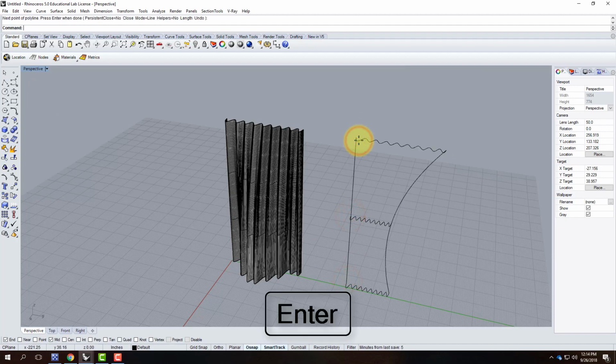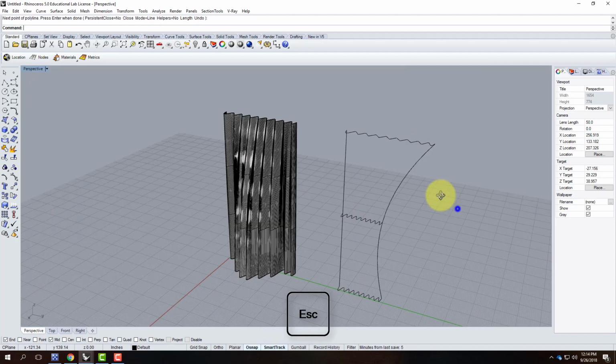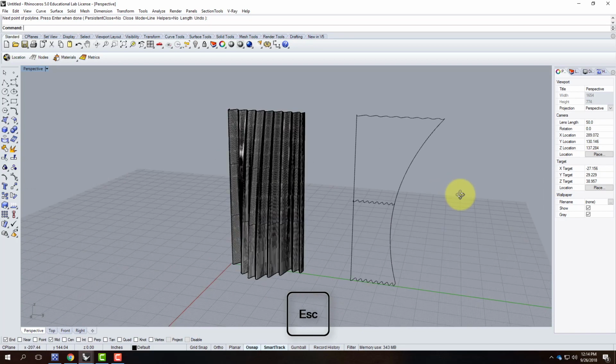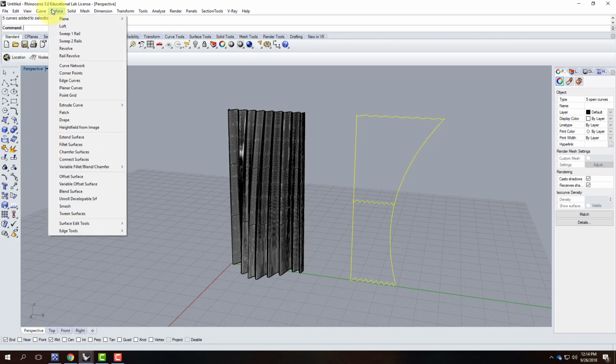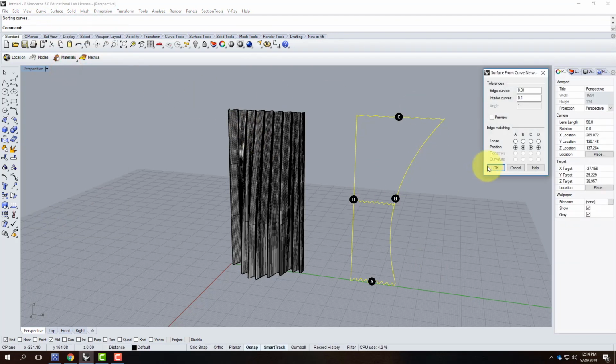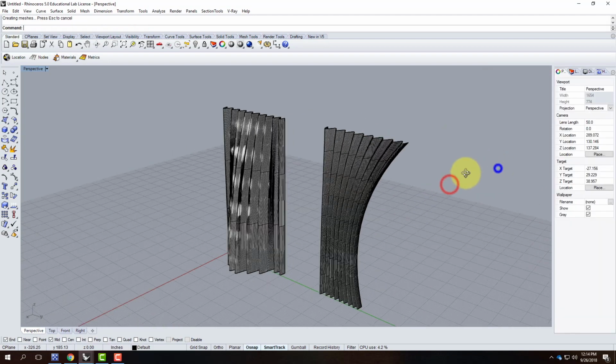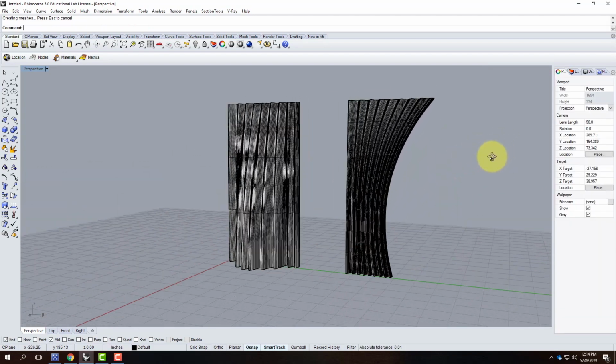There, there, and there. That ends up being a straight line. This is looking an awful lot like a network surface now. So I can do the same thing where I take these pieces and I go to curve, surface, curve network, and I can build that in that context. Now I would probably need something to tie the curtain back that causes this to feel like it's being pulled. But you see how I'm using these same strategies to create this?